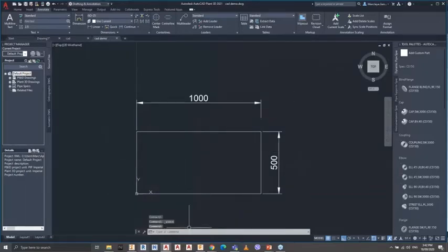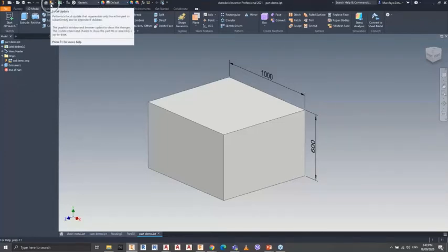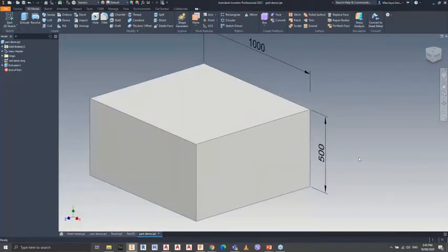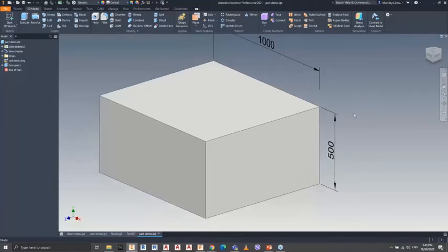And then going back to my Inventor, you don't have to worry about manually modifying each part of your drawing, because by just simply clicking a single button here, which is our local update, you can automatically convert it. Okay, so that's it. We have our AnyCAD interoperability or connection from AutoCAD to Inventor.